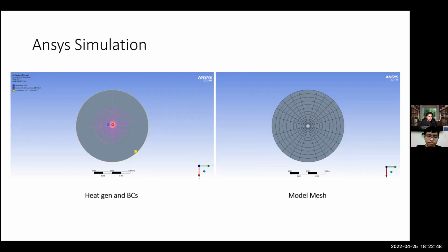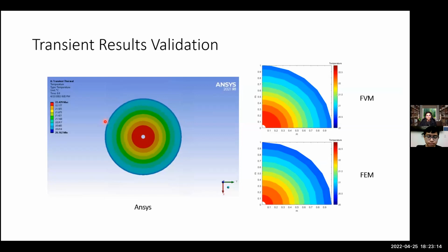As you can see here, they're labeled A through C. If we start with the A condition, it was basically adding an insulation to the center of the charging pad. Then B is this pinkish mesh that surrounds that inner shaded region. That's the actual internal heat generation. And then we implemented a C boundary condition, which was the convection that occurs at the boundary of the charging pad.